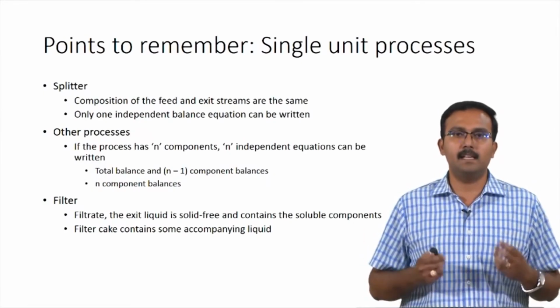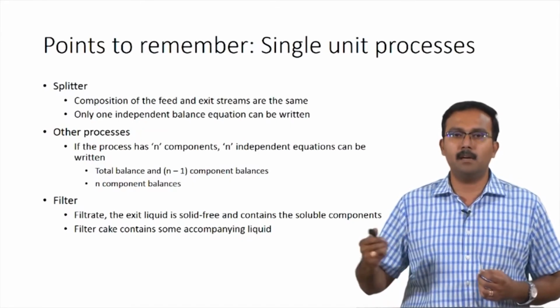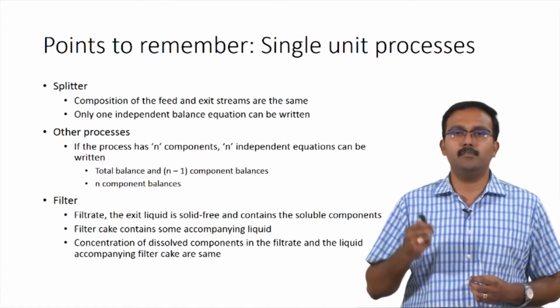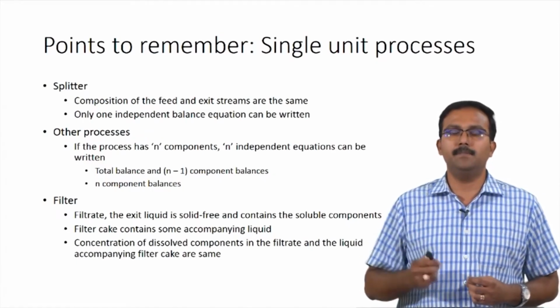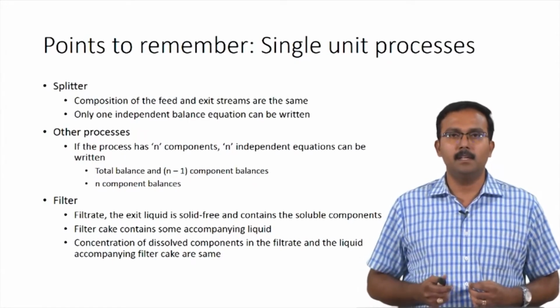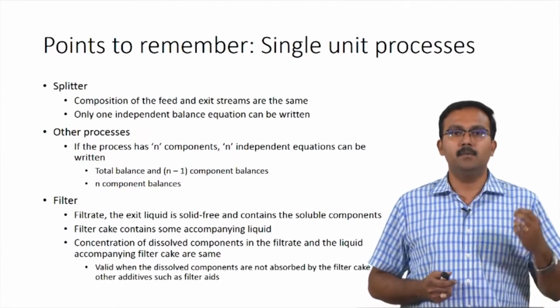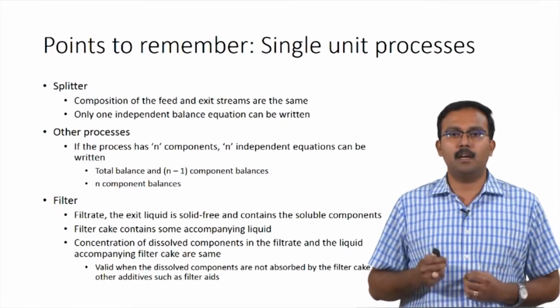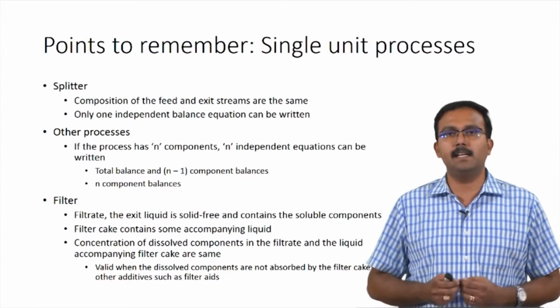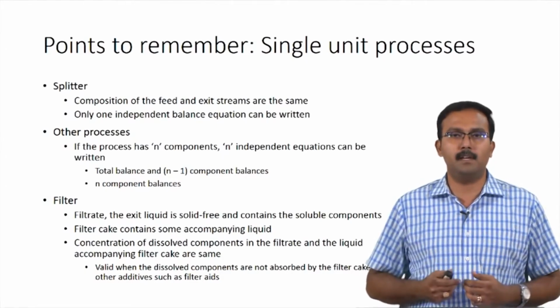The filter cake is the solid which has some accompanying liquid. We need to understand that the concentration of the dissolved components in the filtrate and the liquid accompanying the filter cake are the same. This is valid when the dissolved components are not absorbed by the filter cake or other additives such as filter aids which may be used during the filtration process.